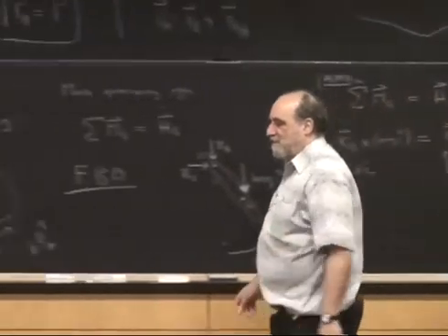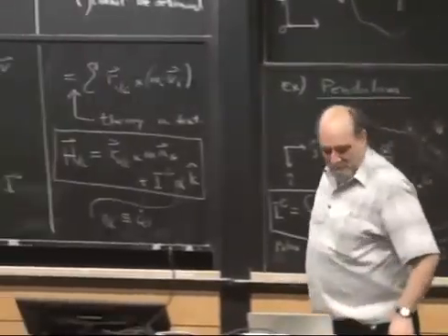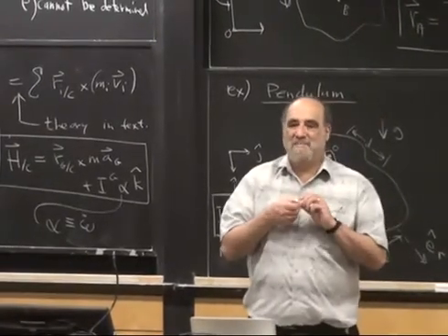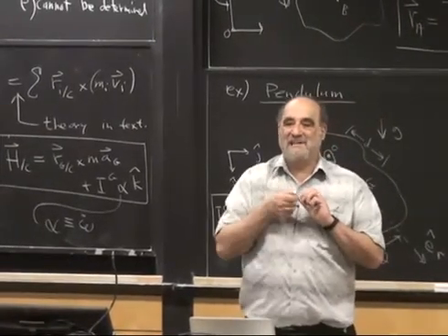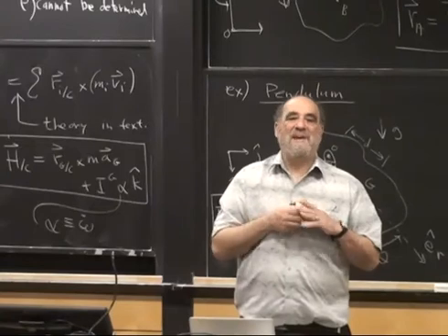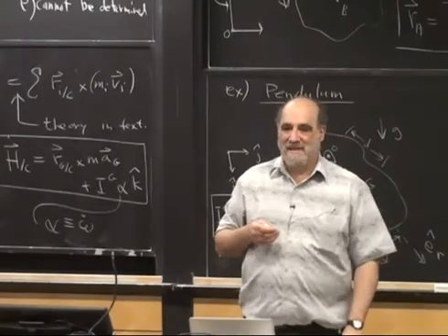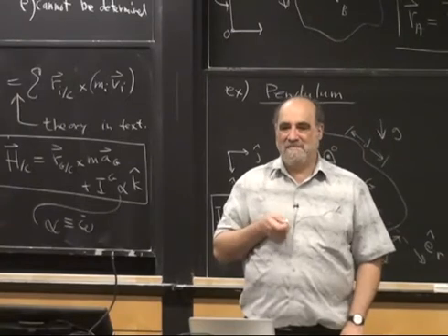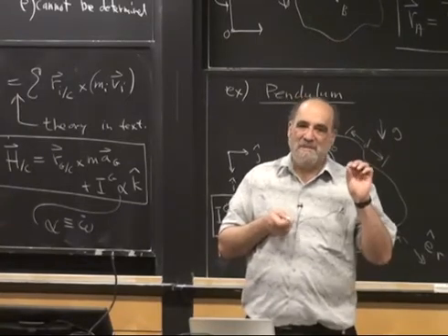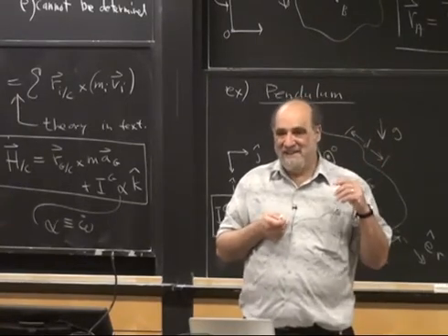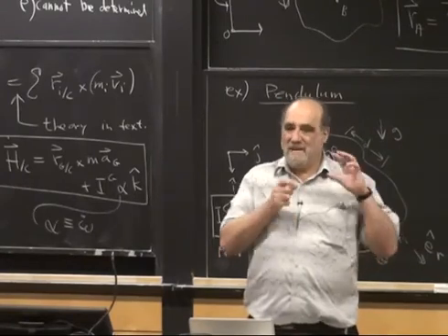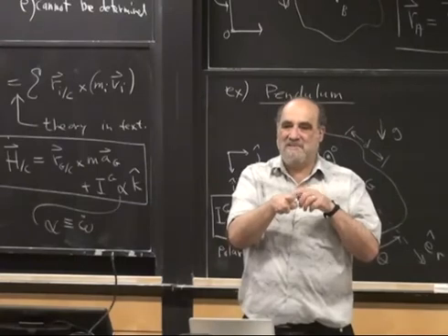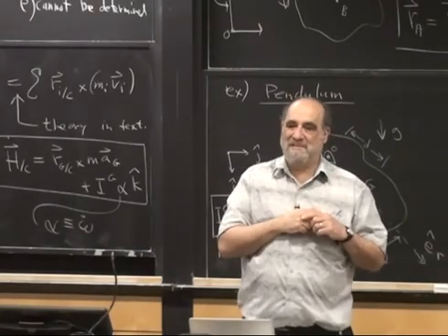When do you use moments about a line instead of moments about a point? When you take moments about a point, the meaning of that is moment about a line in the k direction. So the moment about a point actually isn't a concept that we've used. We're always using moment about a line. In 3 dimensions, moment about a point is a vector quantity. And each component of that vector is moment about the line, x-axis through that point, y-axis through that point, z-axis through that point.